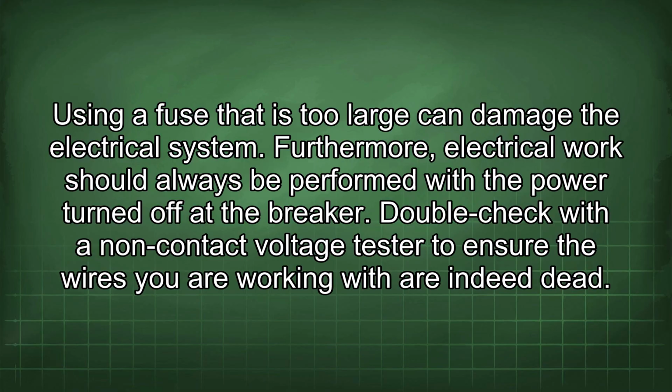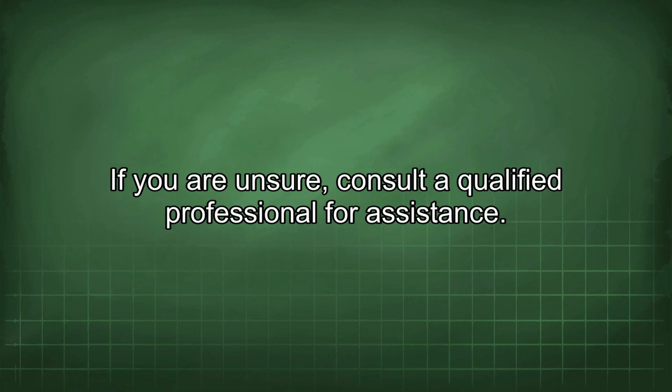Furthermore, electrical work should always be performed with the power turned off at the breaker. Double check with a non-contact voltage tester to ensure the wires you are working with are indeed dead. If you are unsure, consult a qualified professional for assistance.